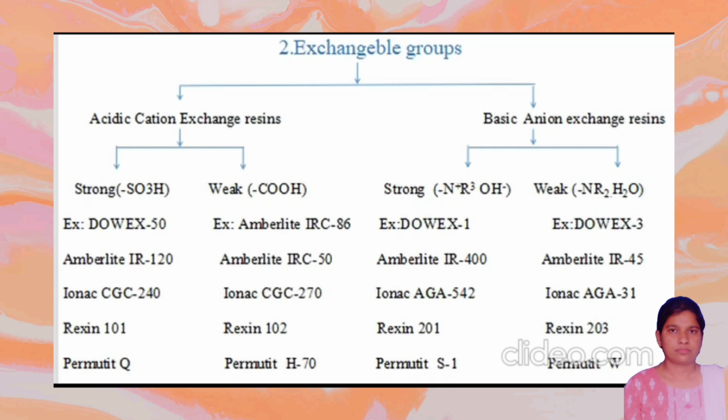The first invented weakly acidic cation exchange resin was used in 1950 for the recovery of the first antibiotic streptomycin from fermentation broth by Waksman, who got Nobel Prize for his discovery. The other examples for weakly acidic cation exchange resins are Amberlite IRC86, which is a gel-type resin used for water dealkalization and demineralization with co-flow regeneration. The other examples are IMAC HP333.